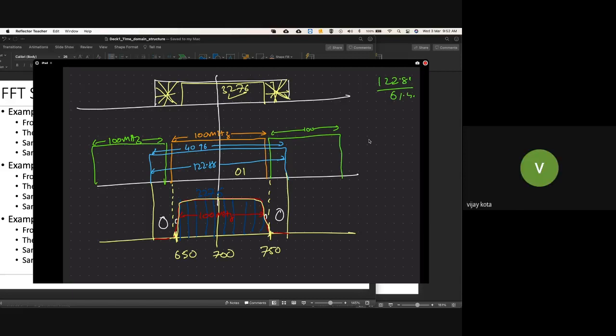No, sir, but over the air transmission, sir. See, this is exactly the over the air transmission. Whether the data is there or not, zeros are also being transmitted, sir. Zeros means nothing. It won't affect your spectrum. There's no power in those carriers. Zero means actual zero value, so there's no power in those frequency bins.